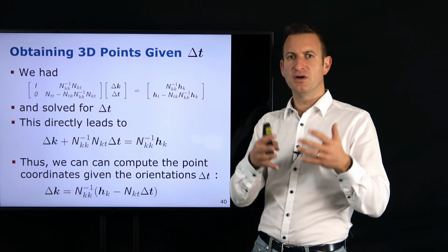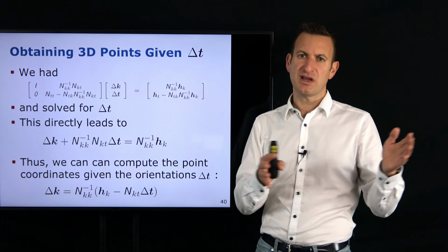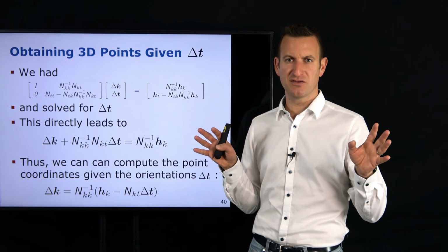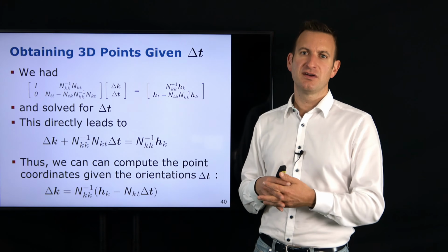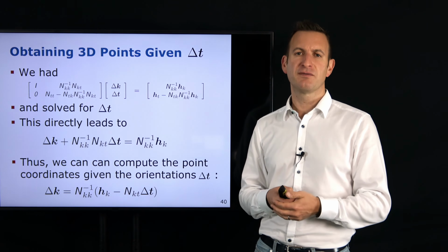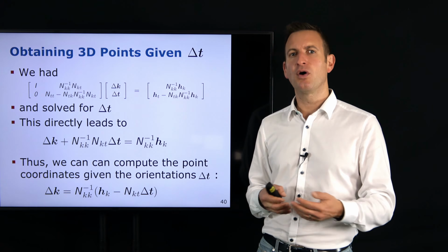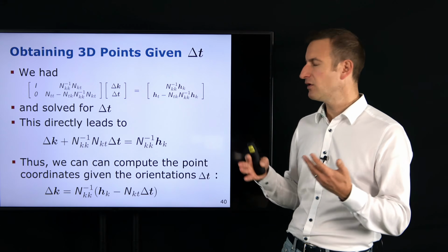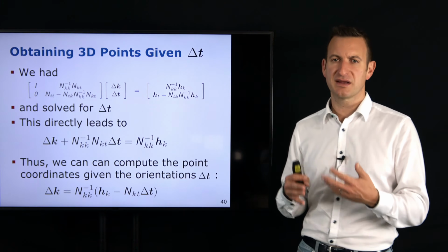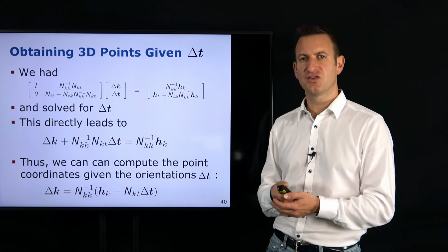This has led me to a normal equation system, which is sparse. And then I could do this trick by multiplying this normal equation system from the left-hand side with this magic matrix, which turned it into a problem that I could easily split up into two parts. First, solving for the camera orientation parameters, and then second, solving for the point coordinates. And all that exploiting the sparsity of those systems. And this is a trick that I'm doing in order to solve this, in theory, very large system in an